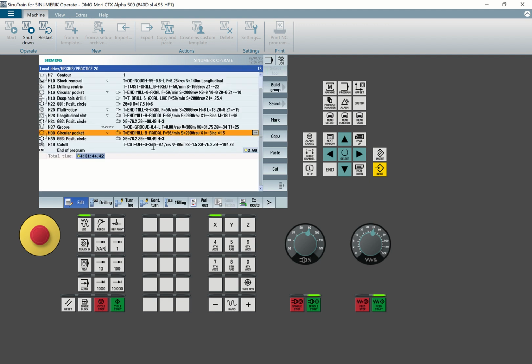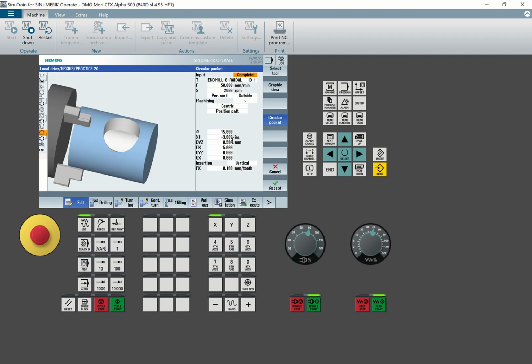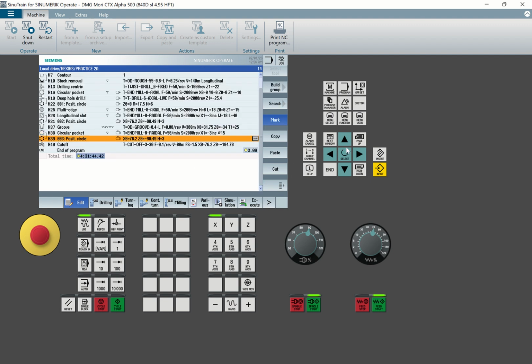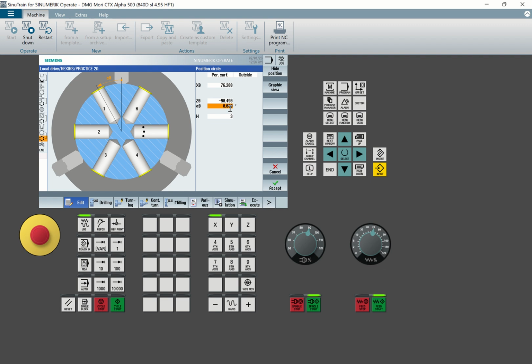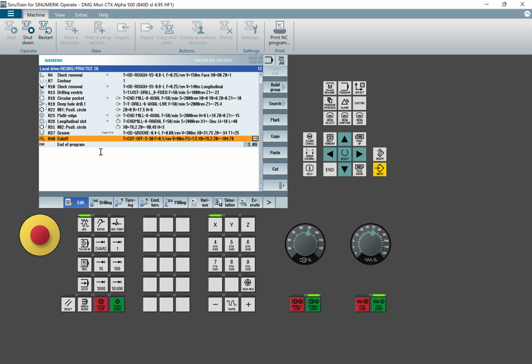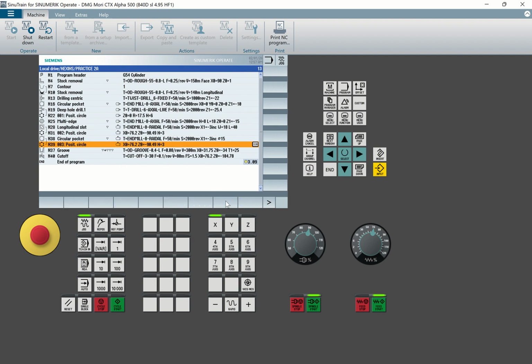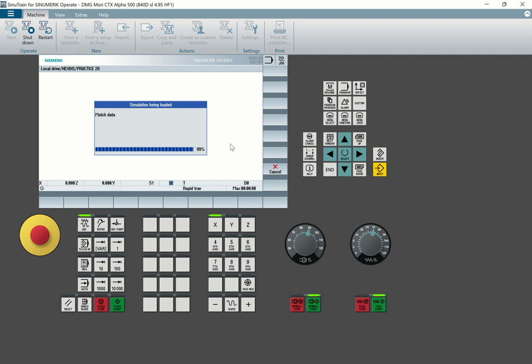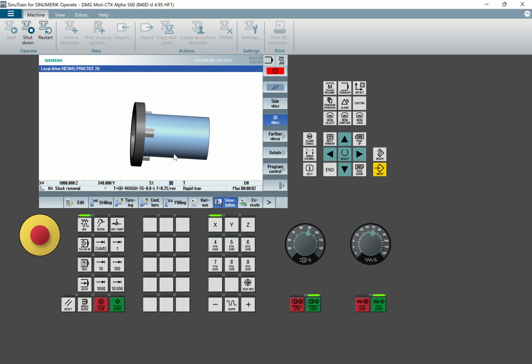For example, here in this one, put the angle 0, but on the positions I have put 0, or I can put even 22.5/2. You'll see what will happen. And then before cutoff, in this program I can do mark with this, and then say cut. Before this, I want to put a mild edge slot, this cylindrical slot. So this one here I want to put first. It comes after that one. Then let me do a simulation. You'll see after that slot, it comes automatically put what I want.